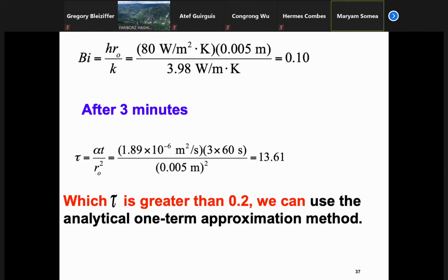Excuse me, sir. Yes. I don't know if I wrote it wrong last class, but I wrote that if the Biot number is smaller or equal to 0.1, we can use lumped system analysis. Here it's equal to 0.1. Is that wrong? Okay, but that's a very good exercise. Yes, it is mentioned less than or equal to 0.1, okay? Again, it's a very narrow range.